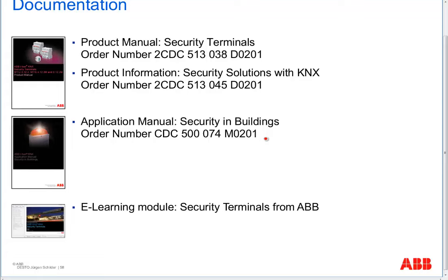Only use the comfort panel to send information, go internal set, or to show the status, maybe on a page protected via pin code, but please use only one logic, in the security terminal. The best thing is to use the security terminals because we have internal set, external set, the same features as in a standard intrusion alarm system. Okay, so far.